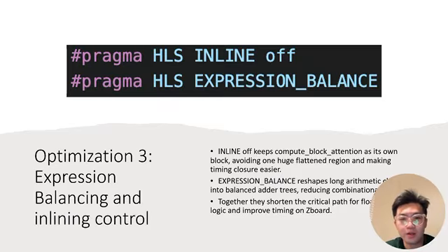The third optimization that I want to talk about is expression balancing and also inlining control. Disabling inline will keep the function as a separate scheduling unit in HLS tools, which helps with timing closure by preventing the entire design from being flattened into one huge block. The expression balancing pragma will instruct the tools to reshape long arithmetic expressions, such as dot products, and also the accumulation of exponentials into a more balanced adder tree.